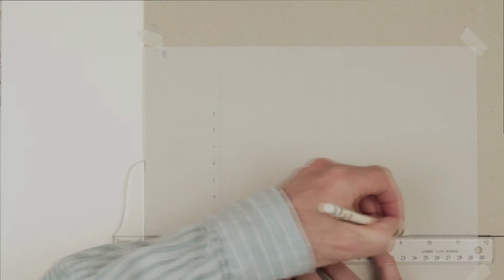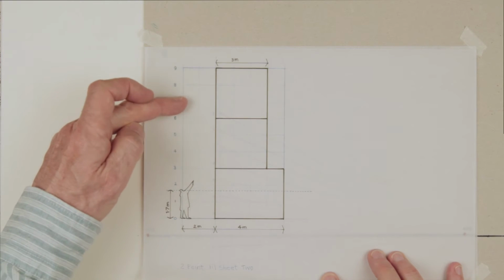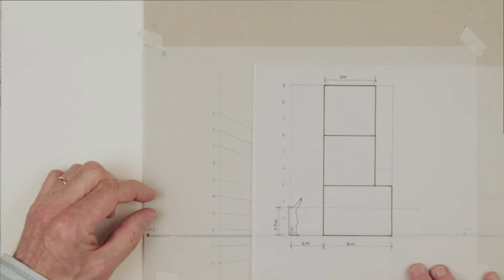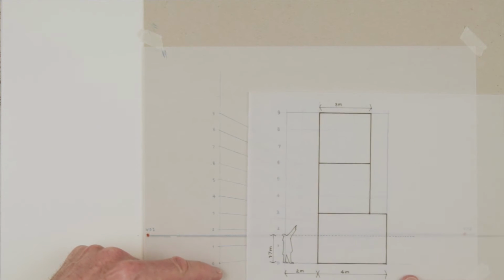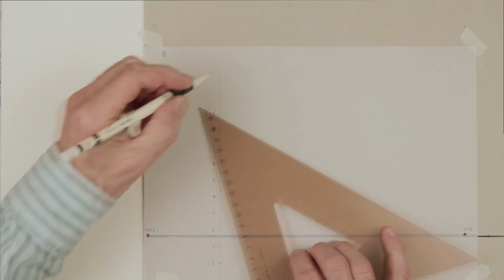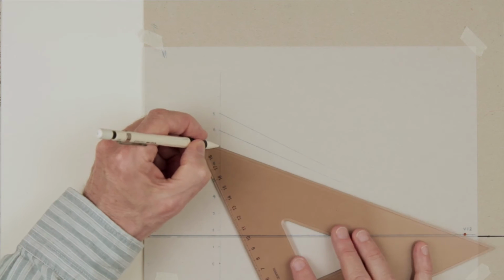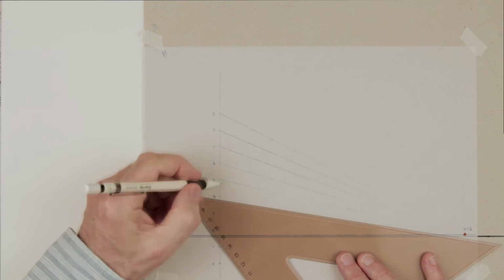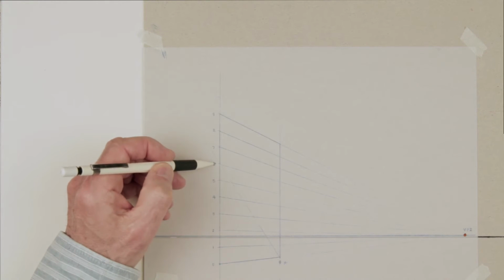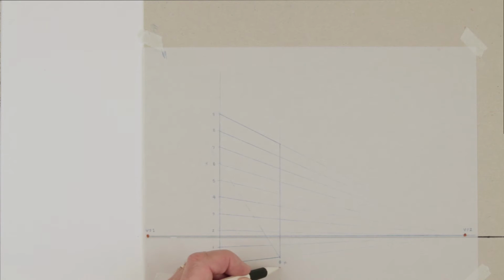In this exercise, we will apply what we have learned to make a drawing of a 9-meter high structure from the viewpoint of a person at street level. In architectural sketches, figures are represented as 1.6 or 1.7 meters tall. So in this grid, the horizon is 1.7 from the base of our shape and literally goes through the eye level of a figure. Start your drawing by projecting all heights on the vertical measuring line back to vanishing point 2. And then estimate a 6-meter distance from the base of your vertical measuring line where your person is stood.